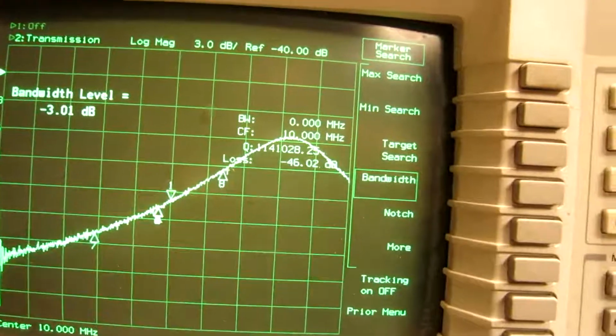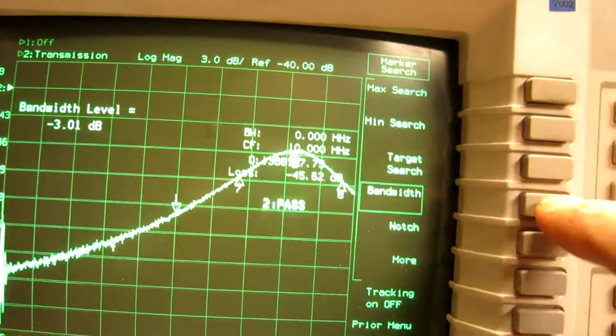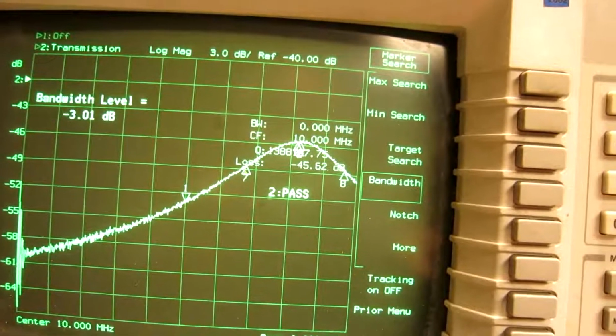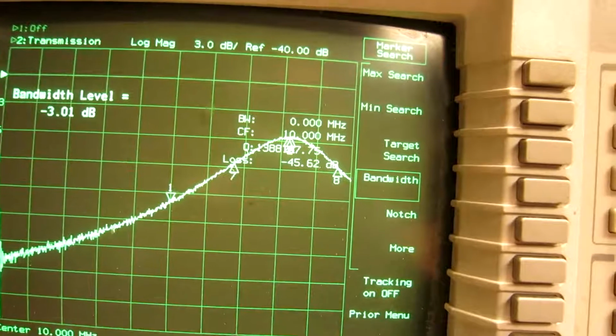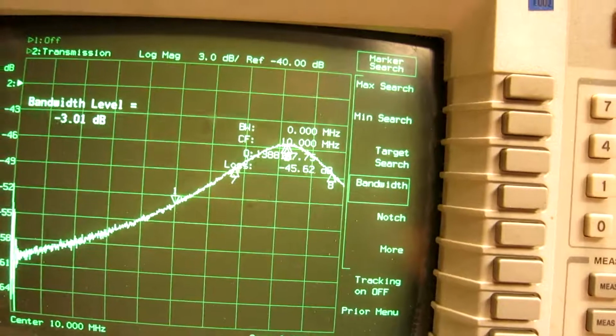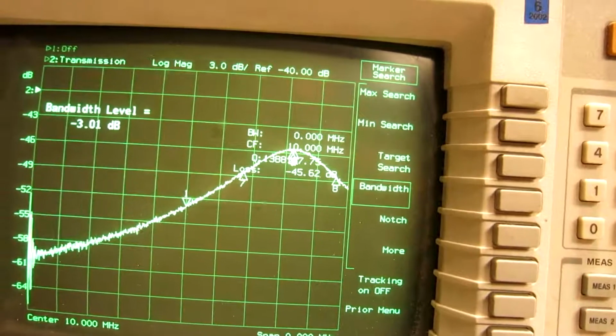And I removed that resistor now. And the capacitance of it shifted the frequency. But I can still see the Q. 1.388 it tells me now. So 1.4 and 1.14 for 1 megohm.